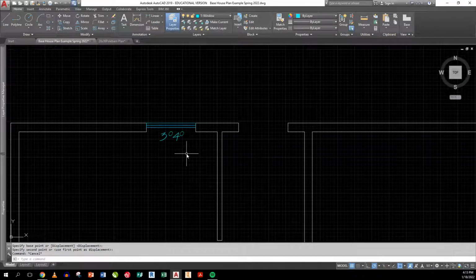Now, these are called builder's dimensions on the symbol. On a residential floor plan, that's fine. On a commercial floor plan, you would absolutely go in and put in a symbol, and we'll talk about that when we get to the commercial end in our class. And then you'd have to build what we call a window and door schedule, or a window schedule just for windows and a door schedule just for doors, which tells which symbol aligns with which door. And so they just have one sheet, the tabulated sheet that shows you all that. So that's all it really takes.